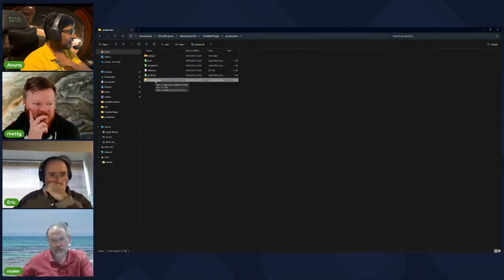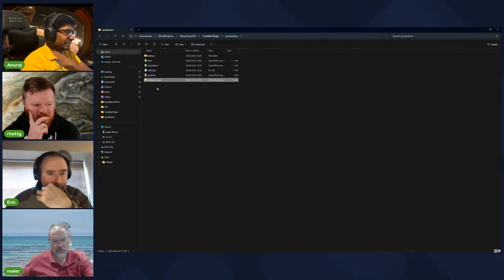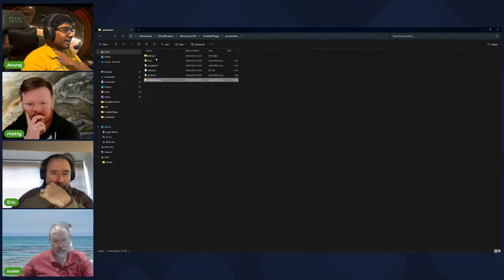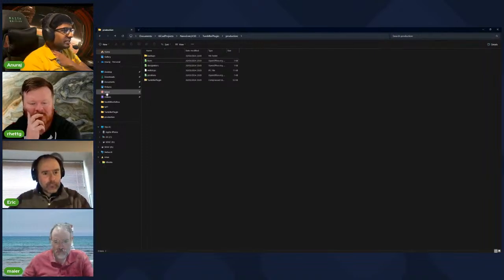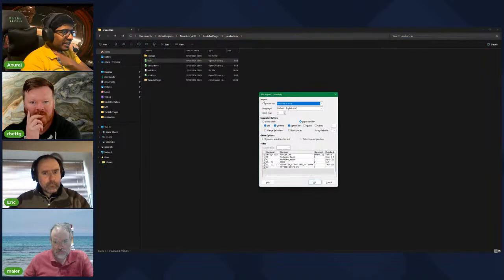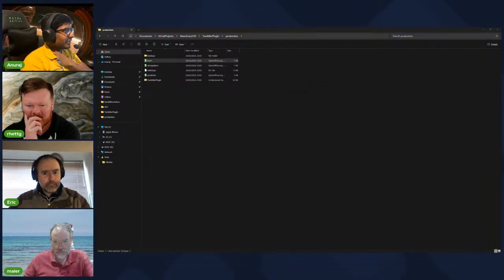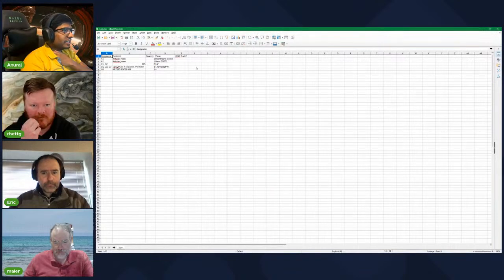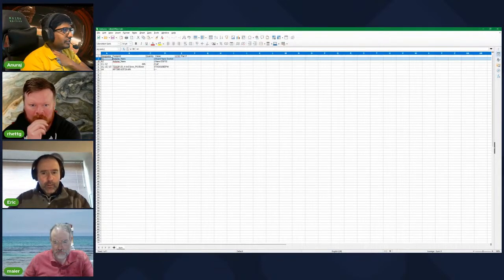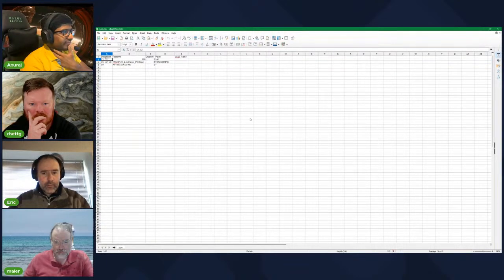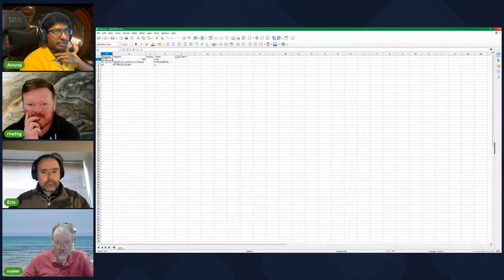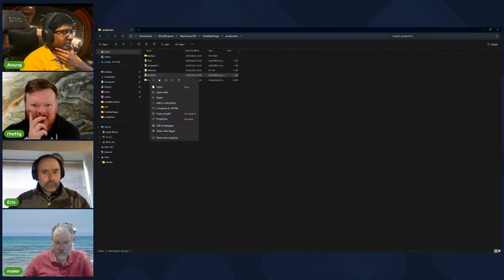Each of the layers will have its Gerber file, and it will put them into a zip file. And then you need the BOM and the positions, these two Excel files, because it has to know where the components are and what components are there. You might need to edit this BOM file, because right now I don't need these two Arduino Nanos. So I deleted these and then save. And then you need to do the same in the positions.